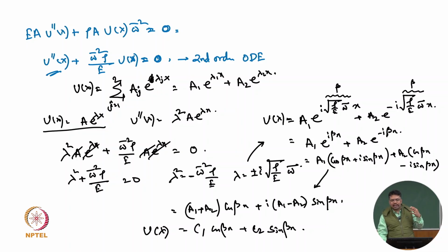In the displacement field, if we try to get the exact displacement field for that system, we also need the boundary condition, because this is steady state vibration, so we do not need the initial condition. But if we try to solve it exactly, we need initial condition. Then from initial condition it will go into the transient state and then it will come to the steady state.